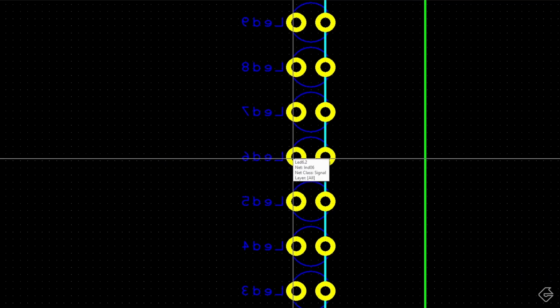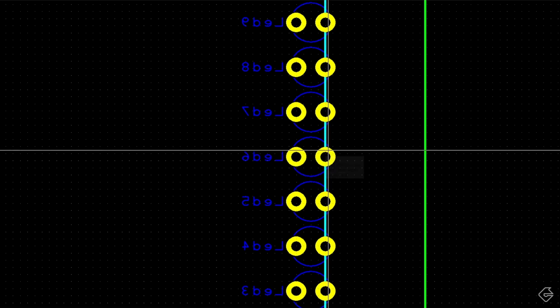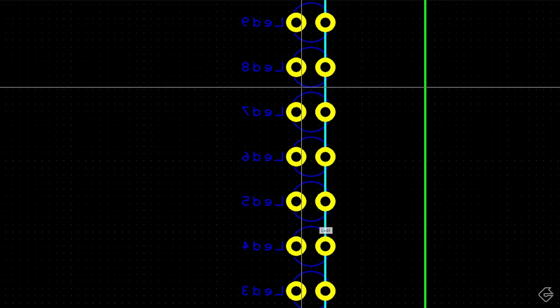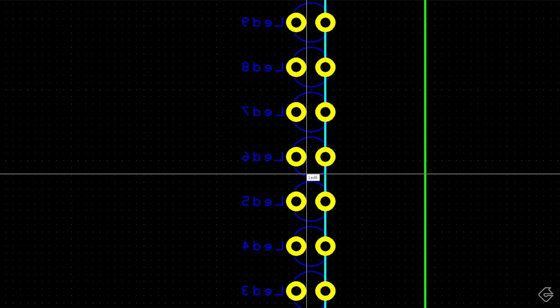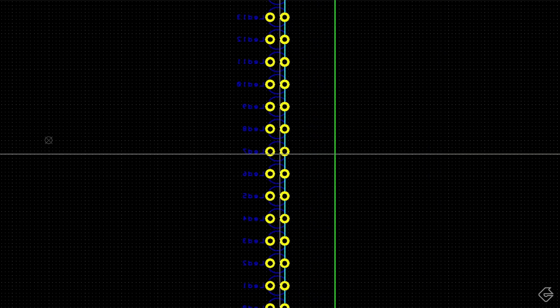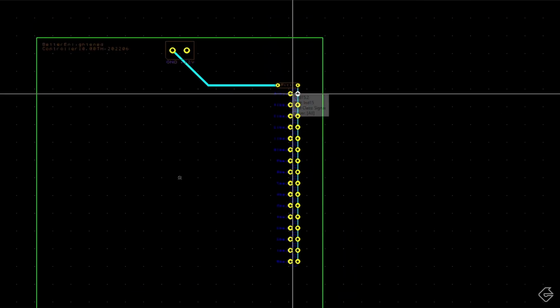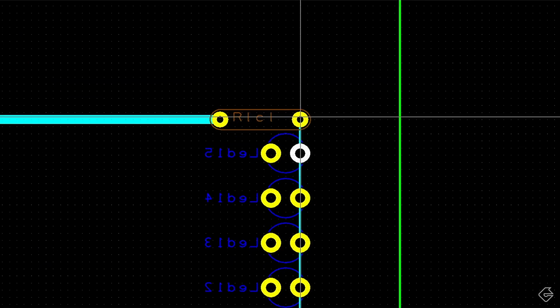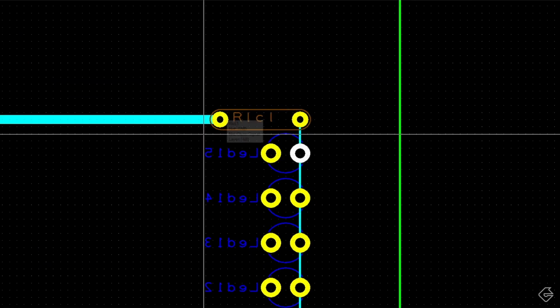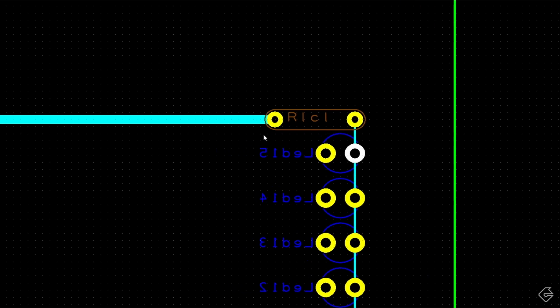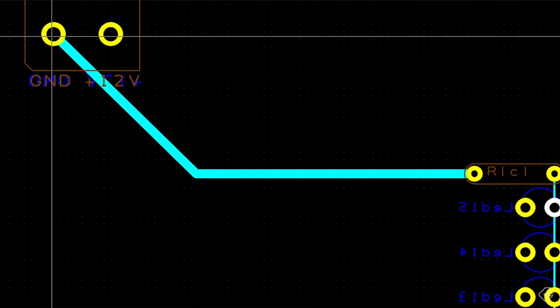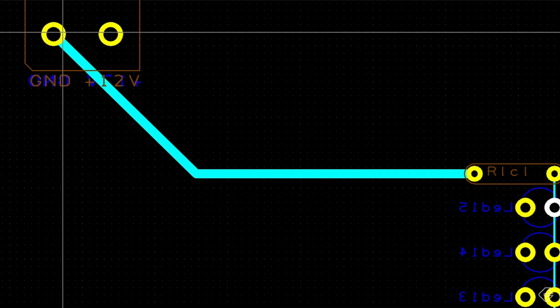And that's exactly what we had on our circuit board. One end of all the LEDs were connected because the way we've designed it is that the current is going to flow through this point to that prong and down through the common, and that's going to illuminate whichever LED has a positive voltage on it. So that's what this is for, and you can see right at the top, it goes down to the end of this resistor, which then goes to the other end of the resistor, which of course limits the current through those LEDs, and it's going to our power supply over here, or where we're going to connect our power supply over here.